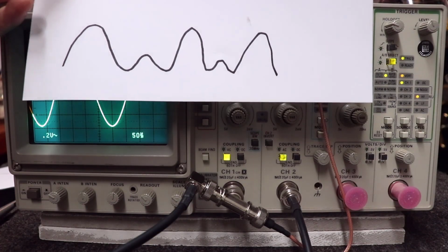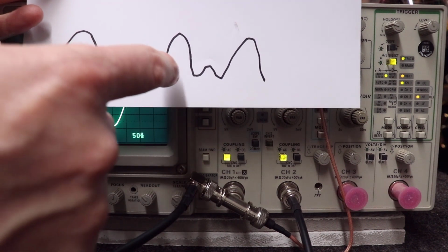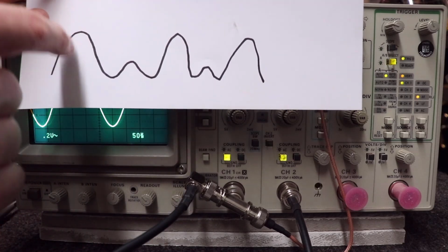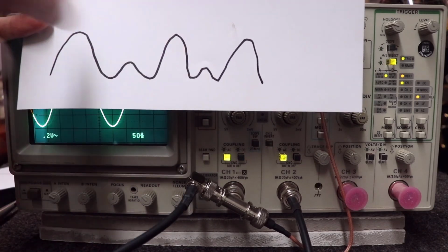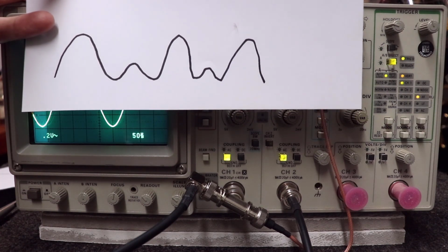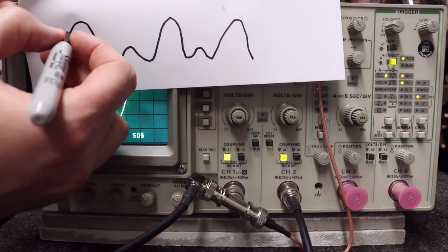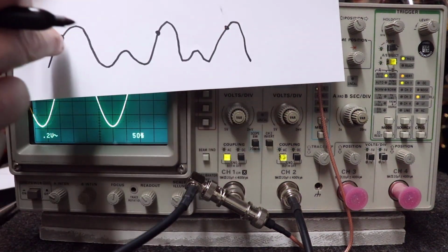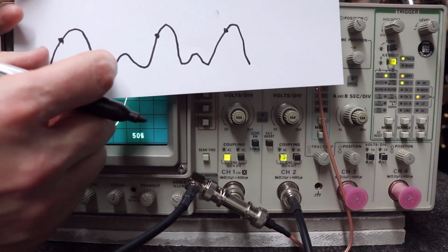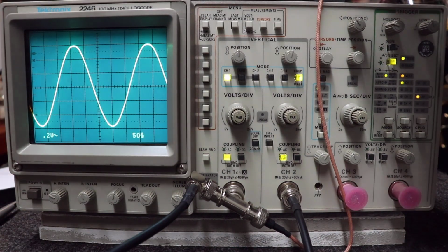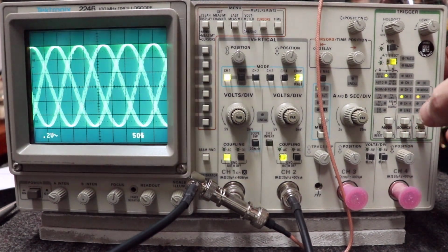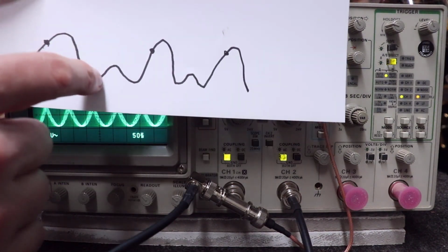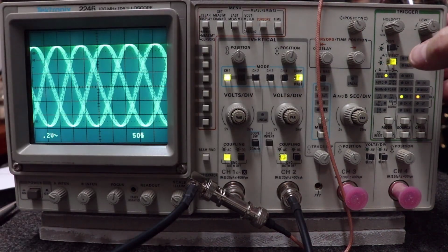What if your signal repeated every certain time base, but the amplitude was different every time it repeated? Say the amplitude was higher every other time. If I triggered on the upswing way up here, guess what? I'm going to be triggering on a signal that is this time base and not this time base. And what I may end up with then, much like I showed earlier, is something that is scrolling like this and not locked on to every single sine wave that's taking place.